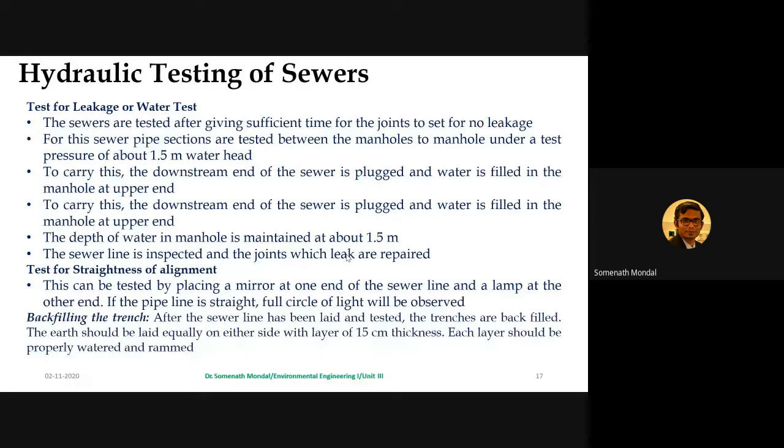However, the earth filling above the crown of the sewer pipes should be carefully carried out by hand, shoveling in layers and using selected soils. Usually, soft earth without any stone, rubbish, or old lumber is used, because if you apply your common sense, you will understand the most important part is the crown of the pipe. The crown is basically the top portion of the pipe.